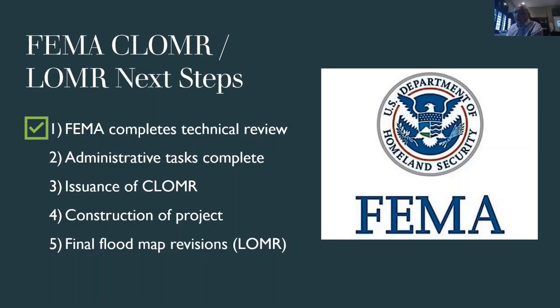A CLOMAR, as we said, is an official letter from FEMA saying they have reviewed the project, it's sound engineering practice, and it meets all of our requirements, including the local permittings and any other federal agency involved. So when it comes to issuing that CLOMAR, the work is done. The proposed project meets all aspects of design and federal regulatory compliance. Okay. Thank you very much.